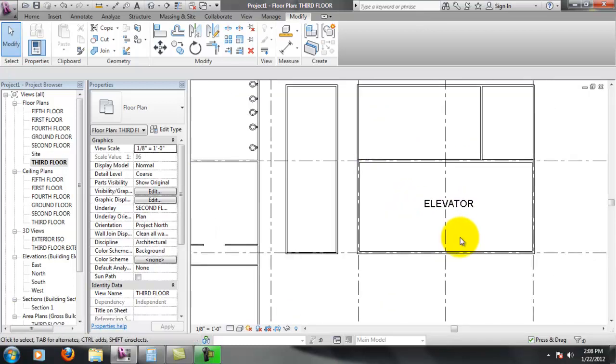I went ahead and did some reference as far as what a standard elevator might take up, and it looks like for 2,500 pounds, you end up with a 5-foot by 7-foot elevator. And with the clearance space on both sides, you end up with a 7-foot 10 or an 8-foot deep core, and each elevator separation takes approximately 6 foot 4 inches.